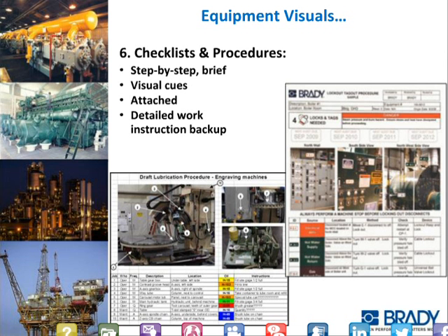And it's laminated and it's posted right next to the machine. Every lube point is numbered in the diagram, but it's also numbered and identified on the machine. And this lube chart or lube diagram actually mirrors what's in the lubrication procedures. So you've got a hard copy posted as well as what is in the lubrication or the PM procedures.